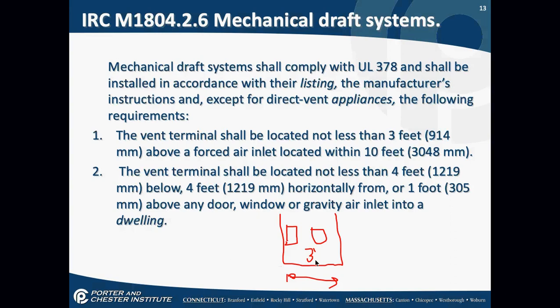Now, I have another group that's right now in air conditioning. I happen to know by having seen design projects, when they did the heat load and everything on their own houses, I saw some pictures. I know 2 people whose houses are in violation of that code. So again, this is a frequently forgotten thing. These people can never open these windows when that furnace or hot water heater is running, because the products of combustion will come right into those windows. So they just decide not to open the windows instead of fixing it?